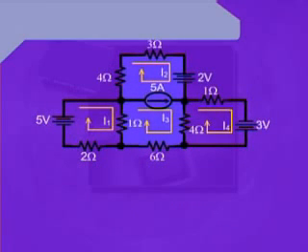Now, one equation is left out, and that is for the coupling independent current source. Therefore, we can write that as well. This is not a KVL equation, but just a simple equation. Therefore, we write minus I2 plus I3 equals 5.